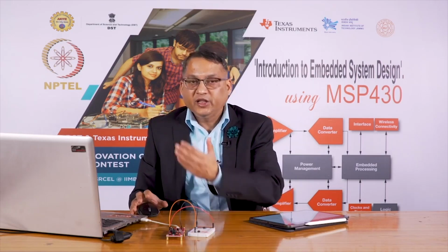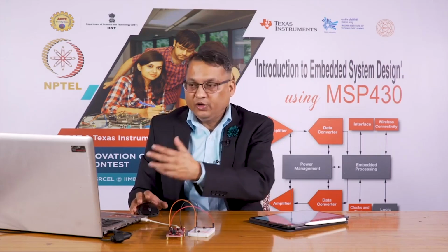The reason I mentioned it is, even though the main program has only one instruction, the question you have to ask is, what does the microcontroller do when that instruction in that main loop is over? The microcontroller has all the necessary ecosystem which supports continued execution of a program, even though you have not provided another instruction to execute.